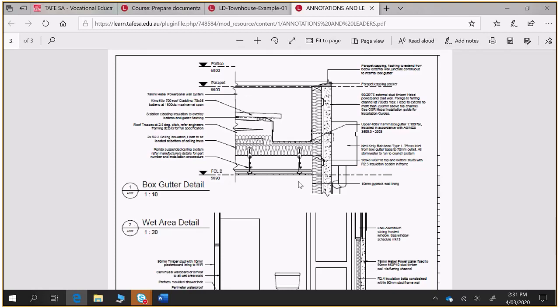So in terms of line weights that I would use for a drawing like this, I'd use 0.5 or 0.35 for that concrete panel. I'd use 0.09 for that sheeting there. I'd use 0.25 for that stud there. I'd use 0.3 or 0.35 for cutting through my stud, and 0.18 for that X to show that. I'd use 0.09 once again for that flashing in the background. I'd use 0.25 for where I'm cutting through the flashing. 0.25 for that timber work there. 0.35 for cutting through that batten, or 0.3. 0.25 for cutting through my sheeting.